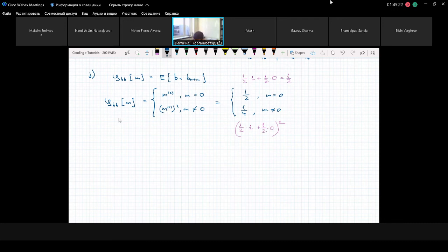Then we go to K. There we say that in the lecture it will be shown that the autocorrelation function of the sample signal can be found by just taking the discrete autocorrelation function and normalizing it by the symbol duration, but in our case, the symbol duration is the same as the bit duration. And yeah, we already did it before. And here we just needed to do it again. And we get the following.